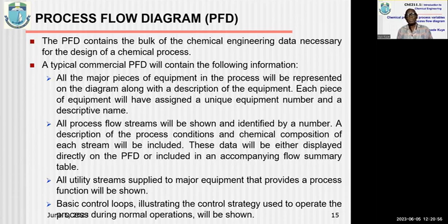And when you look at a typical practical PFD, it will have the following: the major pieces of equipment in the process represented with each piece being assigned a unique equipment number and a descriptive name. The process streams are all shown and identified by unique numbers.